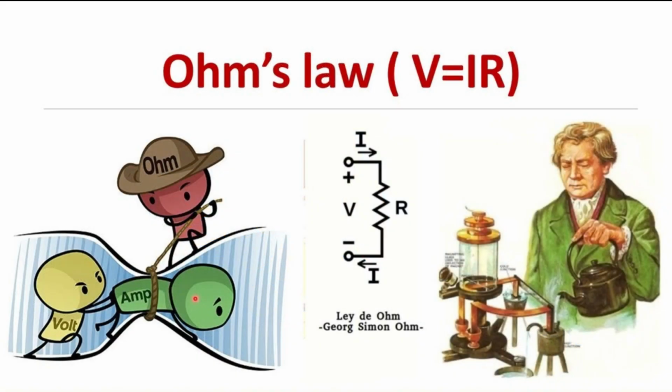Most types of resistor are linear devices that produce a voltage drop across themselves when an electrical current flows through them because they obey Ohm's law, and different values of resistance produce different values of current or voltage. This can be very useful in electronic circuits by controlling or reducing either the current flow or voltage produced across them. We can produce a voltage to current and current to voltage converter.